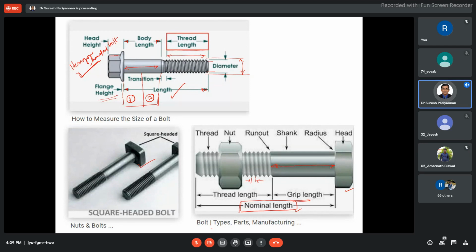But it depends on the nut and on the material. People try to avoid that stress concentration effect. That's why we use washers and flange headed bolts, to avoid that kind of issue. But still we cannot avoid it 100%. Okay, this is one disadvantage.